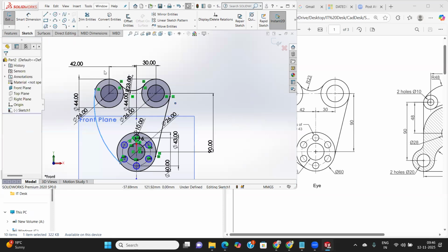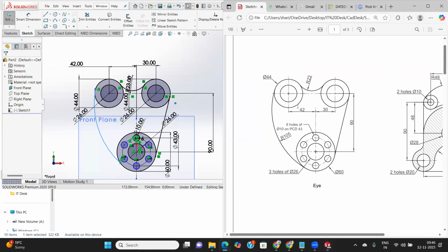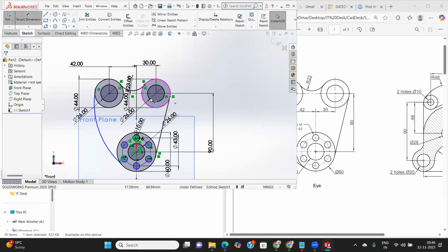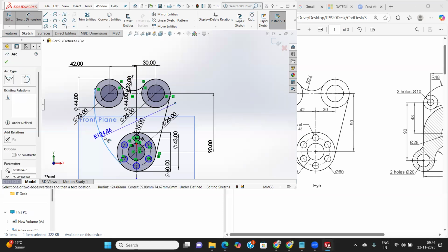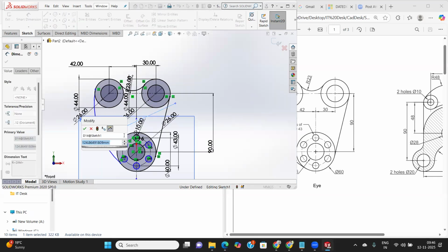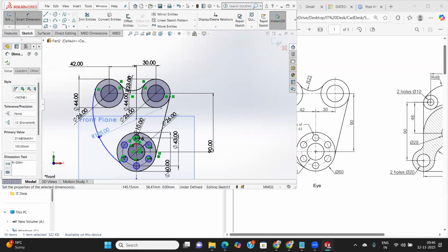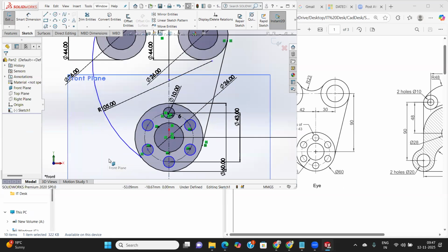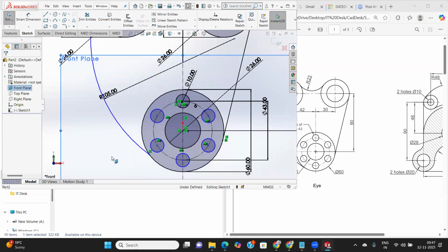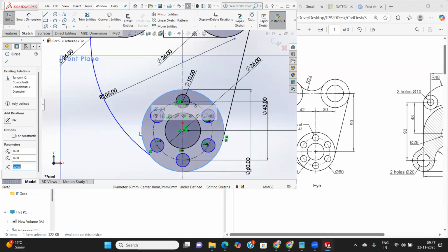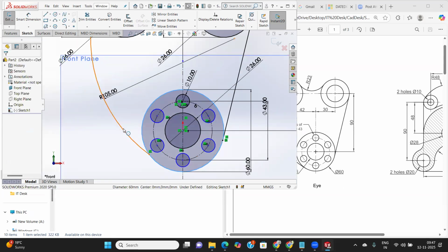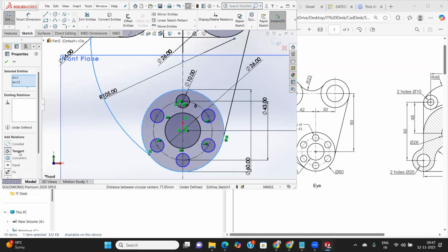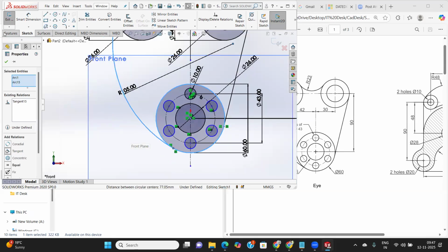And then what we do, first of all, I assign the radius. Radius is 105. So use a dimension and click on it. And then write radius is 105. And after that, make a relation between them, tangent relations, right? Then what you do, select the big circle. Select the first circle. After this, select the second arc. And then what you do, make a tangent relation. Tangent.